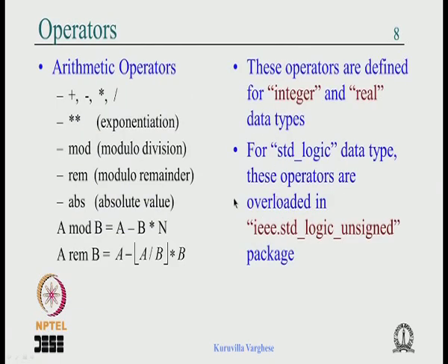Then you have arithmetic operators: plus for add, minus, multiplication, integer division, and exponentiation, because many times we work with powers of 2. Suppose you have a data bus which is 8 bits wide, then you know that it can take values from 0 to 2 raised to 8 minus 1. That is where exponentiation operators are useful. Then you have modulo division, the remainder, and then the absolute value.